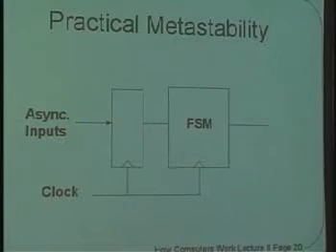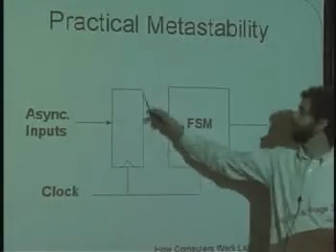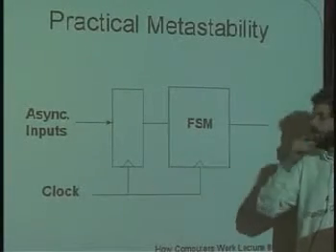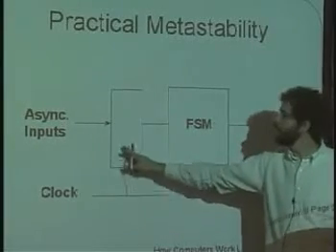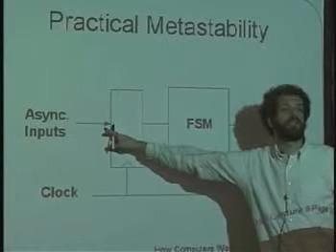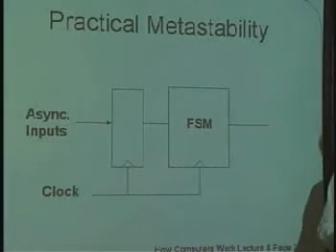Okay. How do we, in practice, actually take care of this issue? Well, I just showed you that we're going to put a flip-flop in front of the FSM that's clocked off of the same thing. We're going to say the clock goes off here. If this input happens to obey the setup and hold time, then everything's fine. We have no reason to think that there's going to be trouble in the first place.